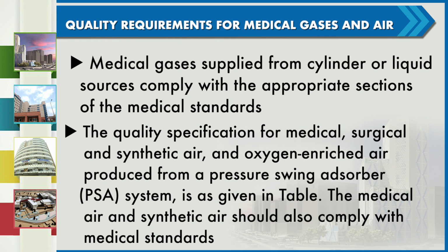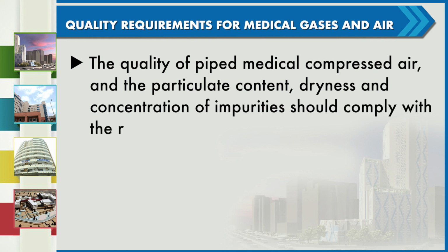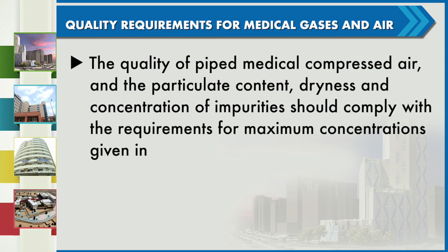The medical air and synthetic air should comply with medical standards. The quality of piped medical compressed air and the particular content, dryness and concentration of impurities should comply with the requirements for maximum concentration given in the table.